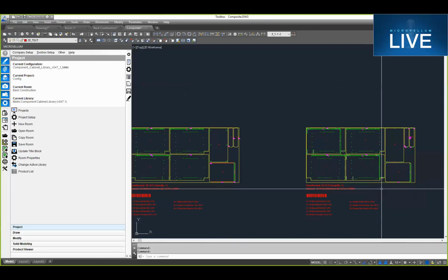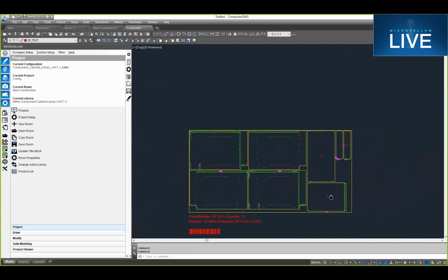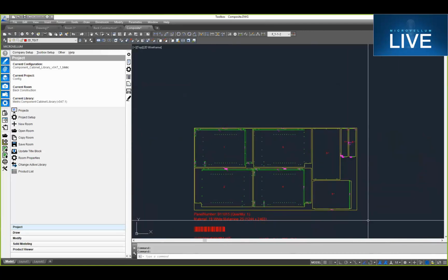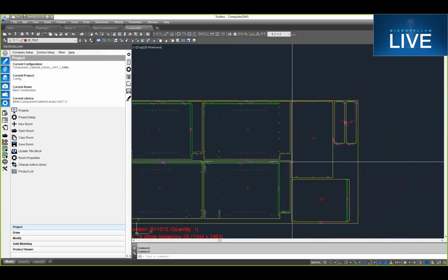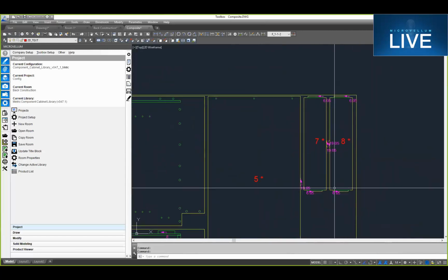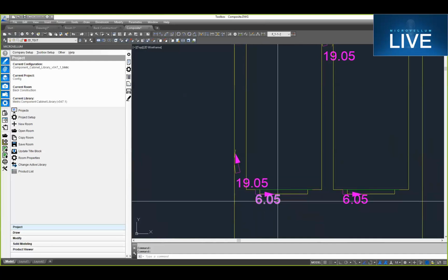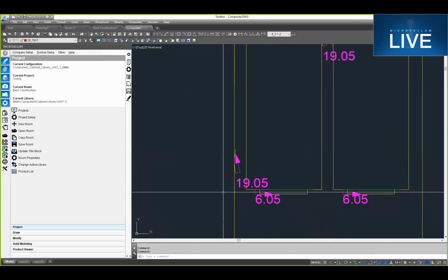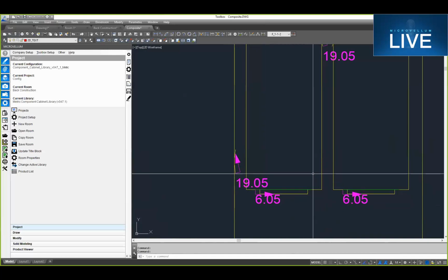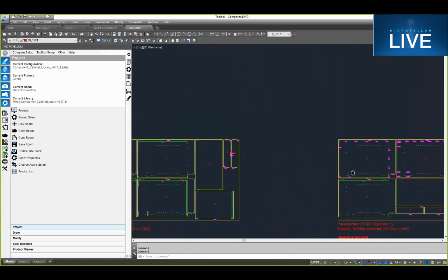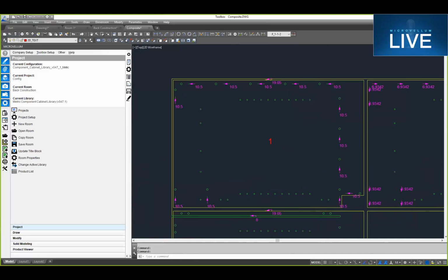And so those are some of the features that are inside of our software here to address some of the machining concerns. So here you can see I've got stretchers, and they're going to cut the notches on there, and then I've got this 6 mil routing to machine that down to its finished thickness as well. And so that's my Dado construction.